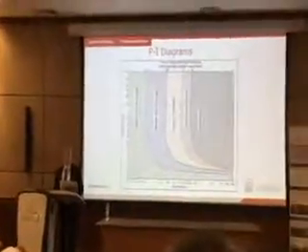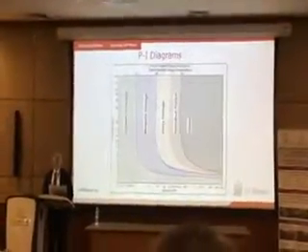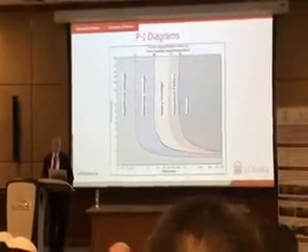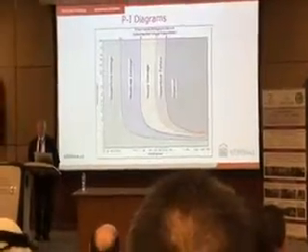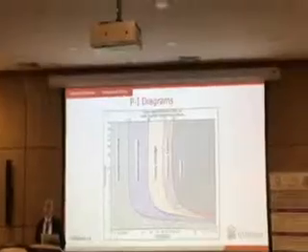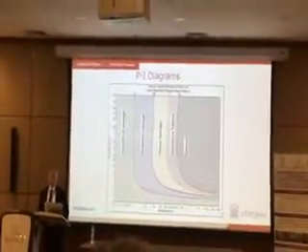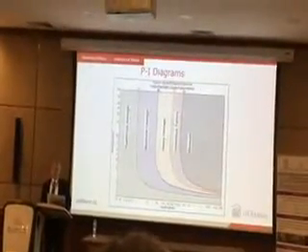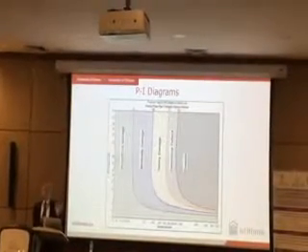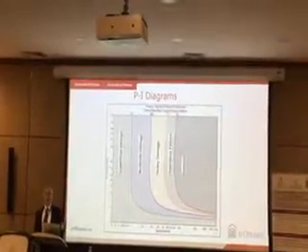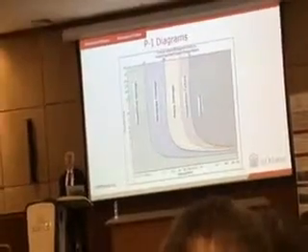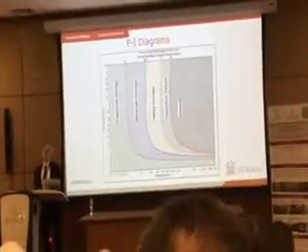Let's say this PI diagram is generated for a column. So this is the pressure and this is the impulse. Given my pressure and impulse, if the intersection lies inside the superficial damage, that's great, nothing will happen. If it lies here, I will get moderate damage. If it lies here, heavy damage, and so on. So if you're in the business of designing buildings for blast, you will have a whole bunch of PI diagrams available.